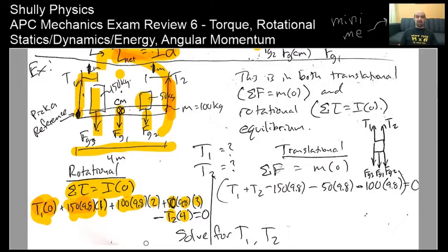So in terms of forming your torque equation, Newton's second law for torque, there are 2 directions. There's positive and negative, which can be like clockwise or counterclockwise, or you might say counterclockwise is positive and clockwise is negative. So just keep it consistent throughout, and go with that. So that sets up your equation, but you have only one unknown, okay? And you can solve for that T2.